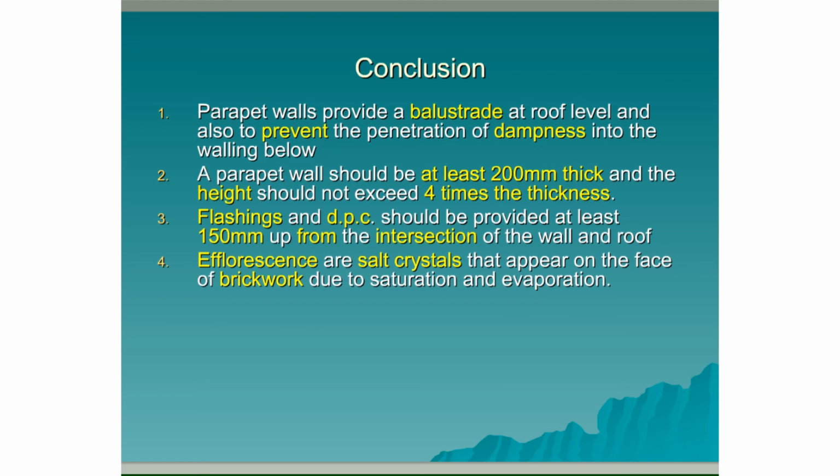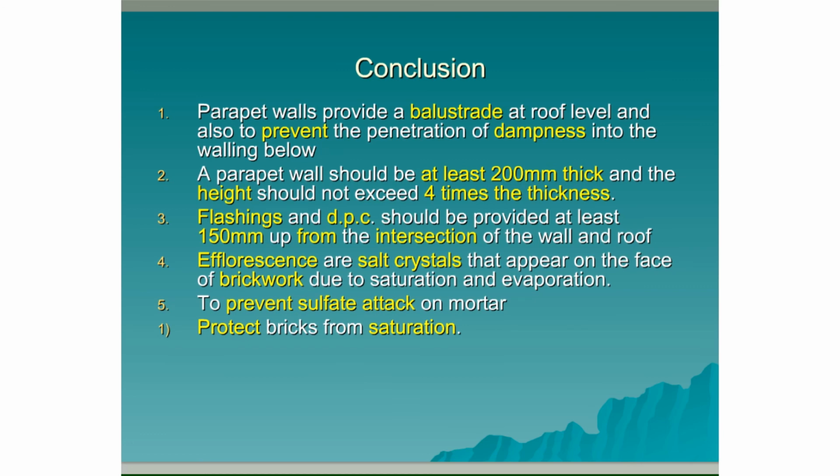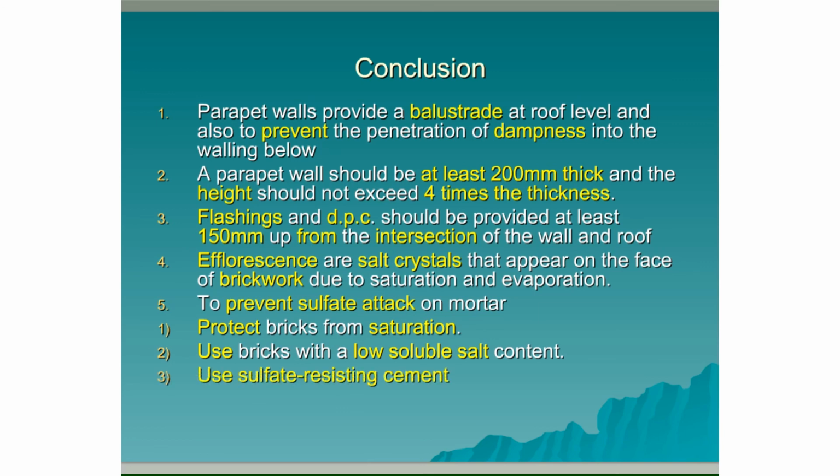Efflorescence is salt crystals that appear on the face of brickwork due to saturation and evaporation. To prevent sulfate attack on mortar, either protect the bricks from saturation, use bricks with a low soluble salt content, or use sulfate resisting cement.